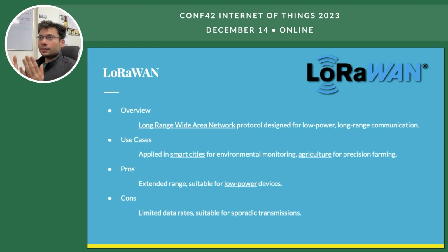This particular protocol offers long range with low power consumption, but at the same time there is a trade-off with the speed. You won't be getting any Gbps or Mbps of speed. Rarely you will get 5 or 6 kbps of speed, but it is still decent if you have basic sensors for which you want to send the data.